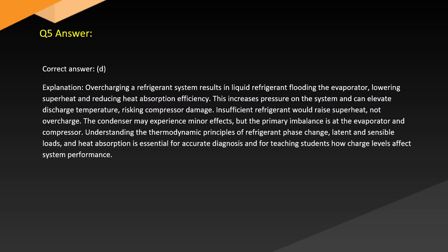Insufficient refrigerant would raise superheat, not overcharge. The condenser may experience minor effects, but the primary imbalance is at the evaporator and compressor. Understanding the thermodynamic principles of refrigerant phase change, latent and sensible loads, and heat absorption is essential for accurate diagnosis and for teaching students how charge levels affect system performance.